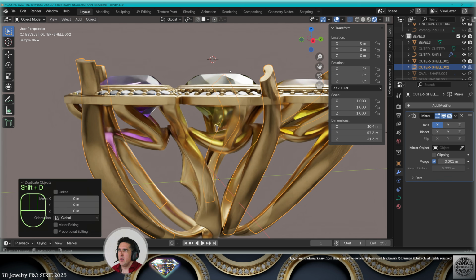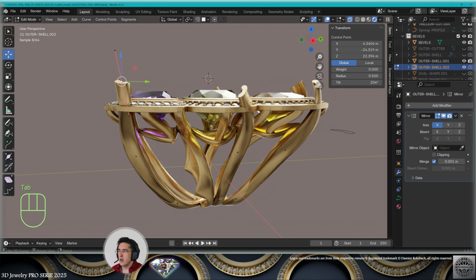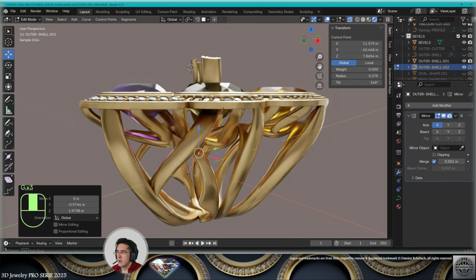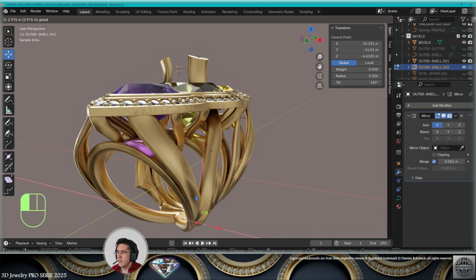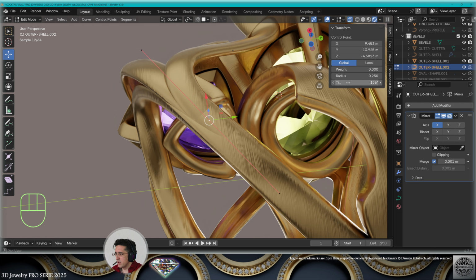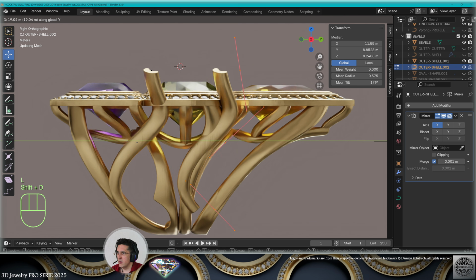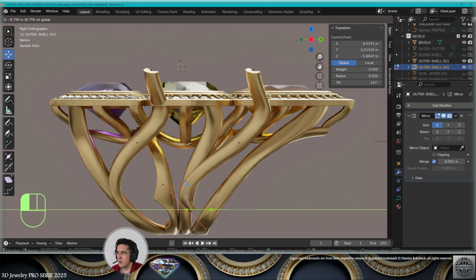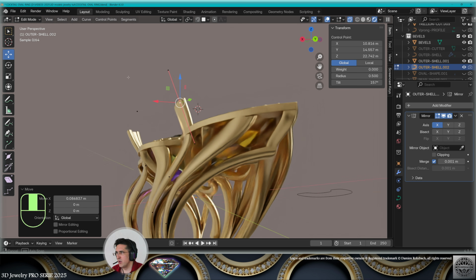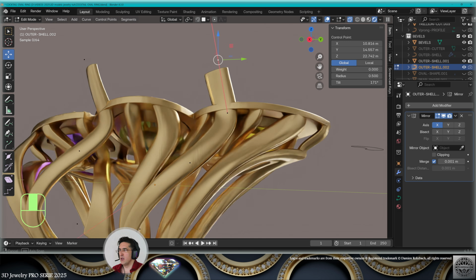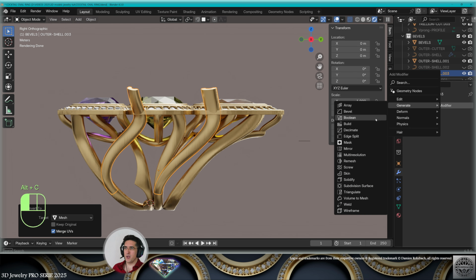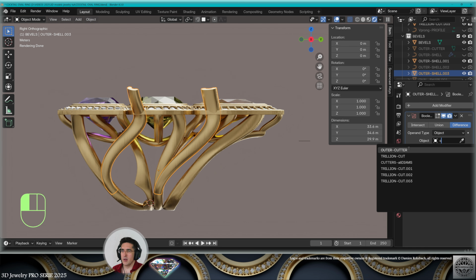Okay, so let's copy the curves, and I'm going to make another set of curves. I think I just want to add something around here to connect with the oval. There, readapt the tilt, and I want the next one to connect from the oval to the pier, and this goes somewhere here. Keep looking from all the angles, check the details. These are ready, so let's make a copy and convert to mesh, add the boolean modifier from the outer cutter.